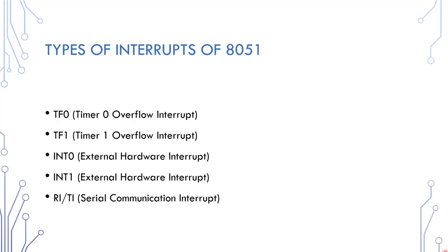Interrupts are events that temporarily suspend the main program, pass the control to an external source and execute their task. It then passes the control back to the main program where it was left off. Each interrupt can be enabled or disabled by setting the bits of the IE register, and the whole interrupt system can be disabled by clearing the EA bit of the same register.